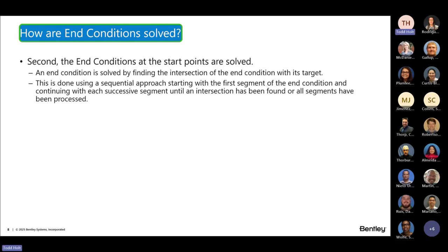So it's first going to look at the first point or the hinge point, to see what the target is. If the target exists, it's going to move on to the point properties, and depending on the point properties for check for intercept and place point intercept, it's going to start drawing out that end condition because everything is met on that particular end condition.